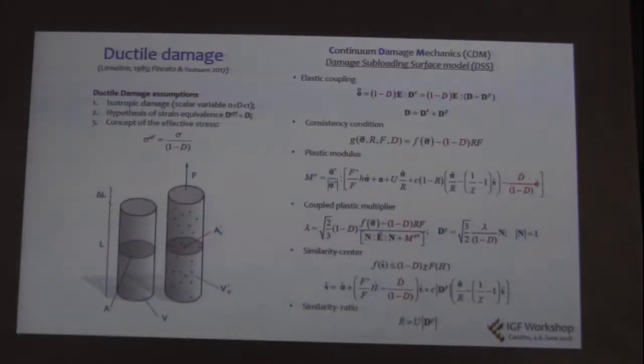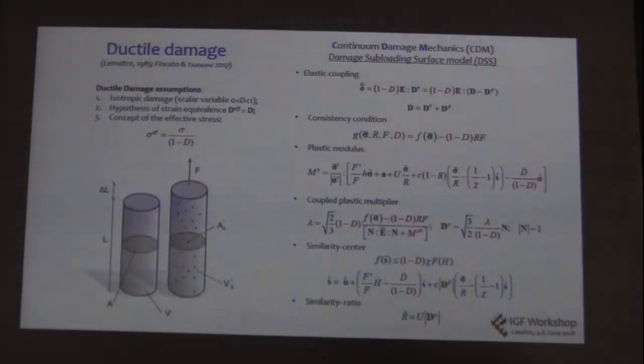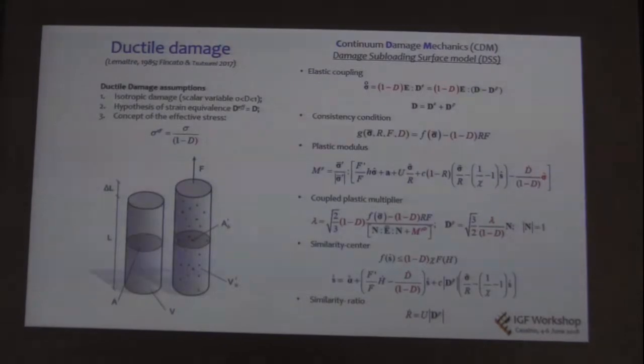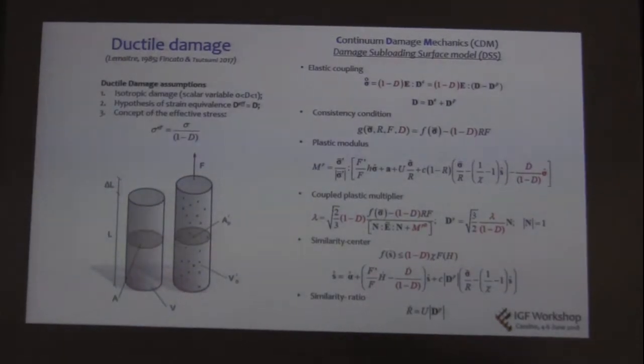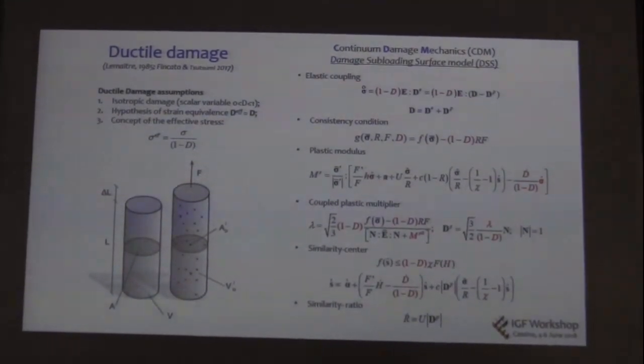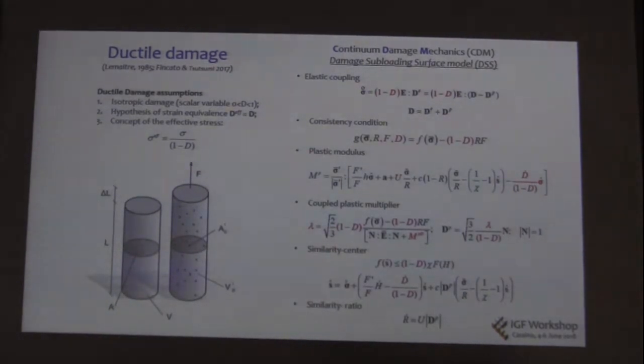stress triaxiality. Briefly, without entering into detail of the constitutive equation, I will just say that the model has been developed in the framework of continuum damage mechanics, assuming the damage as an isotropic scalar variable and assuming all the hypotheses that have been proposed by Lemaitre. And just for sake of completeness, I will say that the damage has been coupled through the definition of the stress rate and the consistency condition for taking into account the effect on the plasticity. Through some mathematical passages, we can obtain the plastic multiplier, which gives the influence of the plasticity and mutual the damage on the plasticity during the analysis.